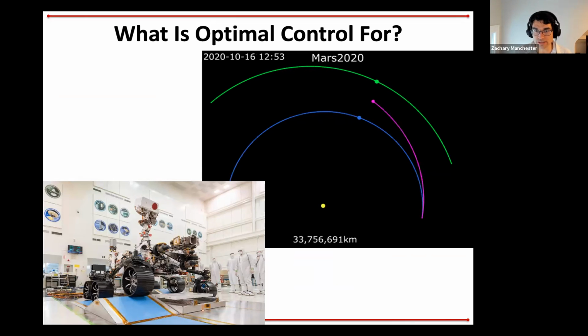The earliest applications for optimal control, where a lot of it was originally developed, are in the aerospace field, which my lab still works in quite a bit. Originally this was developed for solving for rocket trajectories for launch vehicles, starting in the 50s and 60s. And then for computing things like, today, how to get to Mars. Designing the trajectories to fly a spacecraft from the Earth to Mars is done with the sort of trajectory optimization methods that we're going to talk about in the class. Specifically, this gets done with nonlinear trajectory optimization methods, often direct collocation.